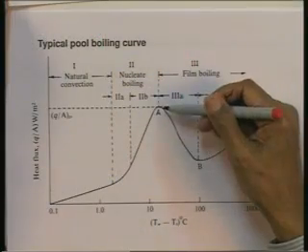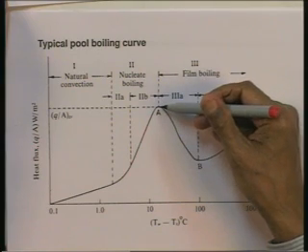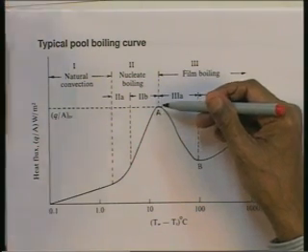Now, the moment that happens, on the heated surface, instead of having bubbles forming, you have a small vapor film on the surface, because they are forming too close to each other, joining up and forming a vapor film on the surface. Now, when partly the heated surface is covered by a film of vapor and partly it is having bubbles forming on the surface, then because of the formation of a film of vapor, the vapor obviously has a lower thermal conductivity.